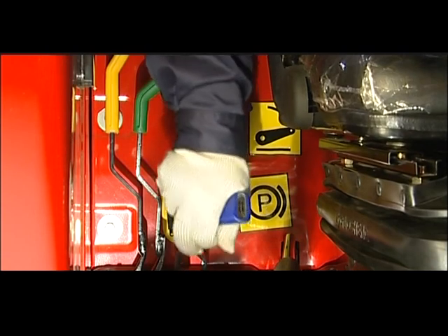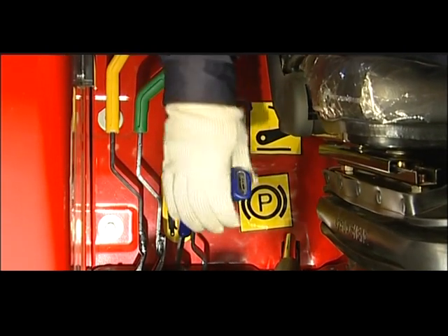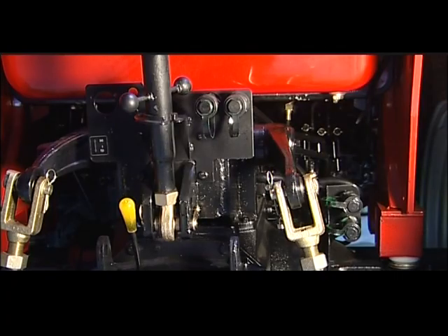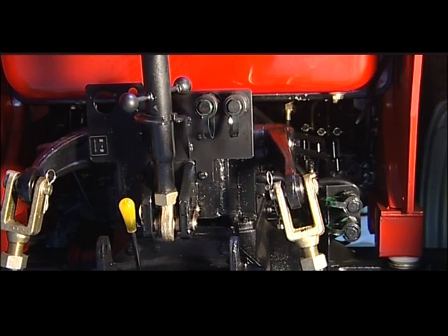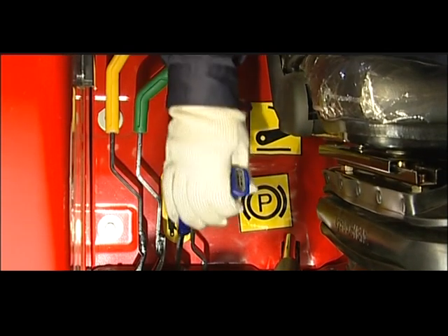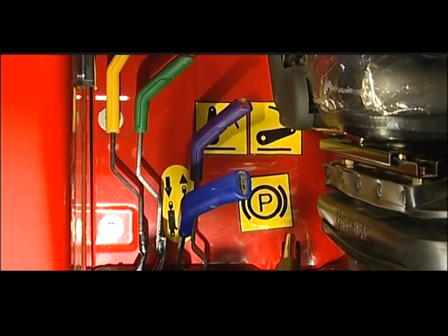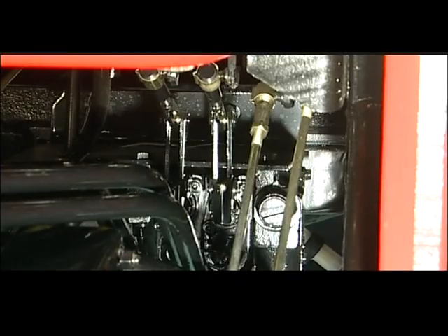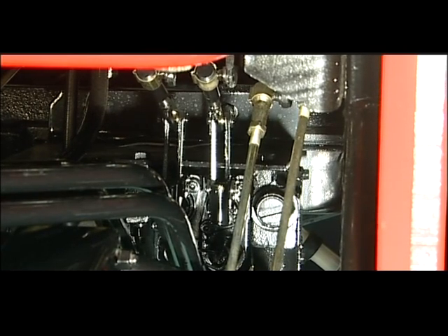Operation of hydraulic output valves. According to needs, the tractor may install 1, 2, or 3 pieces of spool hydraulic output valves. The 2 pieces of valves can mostly be selected for strong pressed type. In the cab, move forward the control lever of the multi-way valve. The multi-way valve piston rod will be pushed by the control connection lever and mechanism linked with the multi-way valve, so the valve oil path is opened.